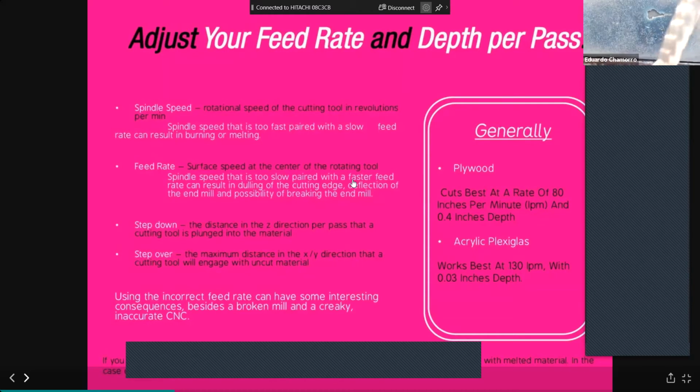So when you are cutting, where is the camera? When you're cutting, this is super clear. You have a big hole inside the end mill. This one flute is really big. So you want to have the flute completely filled, like fill the whole spoon of the end mill. So actually you get a lot of heat exchange, and so the material doesn't heat. So in that case, you also want to go to the lower RPM.